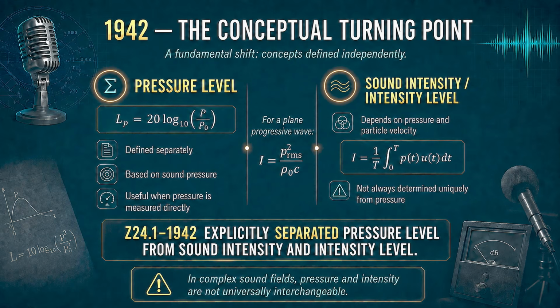But here is the important point. This relationship only holds under certain conditions. In standing wave fields, near fields, and other complex sound fields, pressure alone does not uniquely determine the actual energy flow. A microphone can measure a large local pressure fluctuation, even when that pressure does not directly tell us how much acoustic energy is flowing through a surface. Pressure is not simply another name for intensity. This is the fundamental distinction.